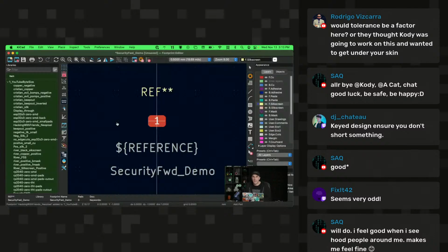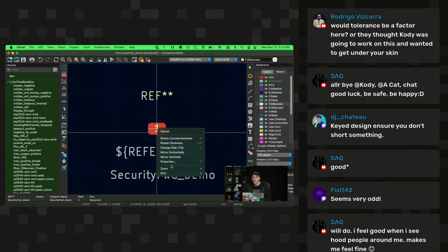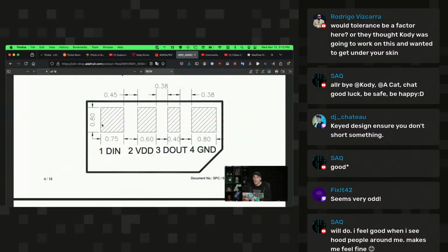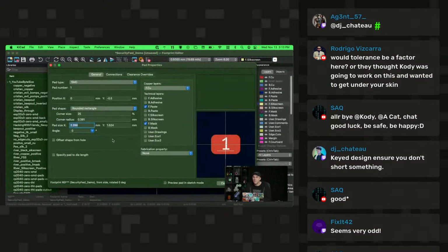All right. Oh, God, I hate math so much. Okay. So this one, I'm going to right mouse click and do properties. And this is the one where I want to make sure that the first one is 0.8 by 0.75. So the pad size is way too big. We need this by 0.8 by 0.75. And then we see what the preview looks like. Wow. 0.8, friends, not 8, 0.8. No, 0.75. What are we doing here? Okay, there we go. That's a little scary.